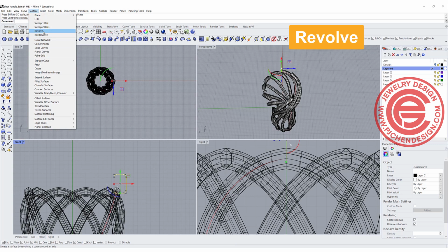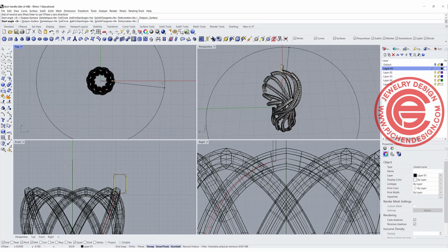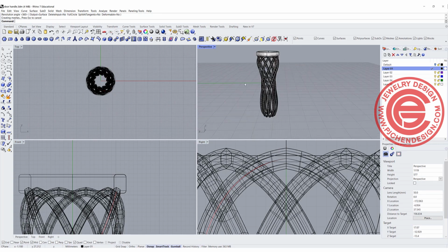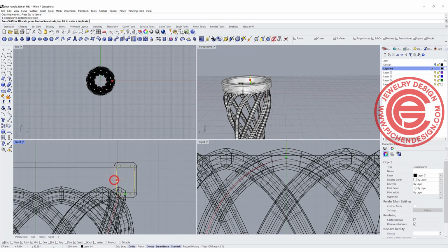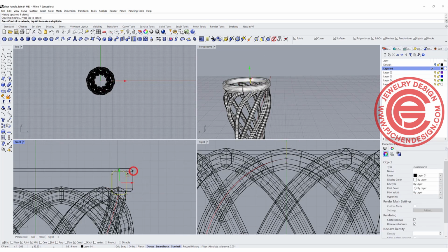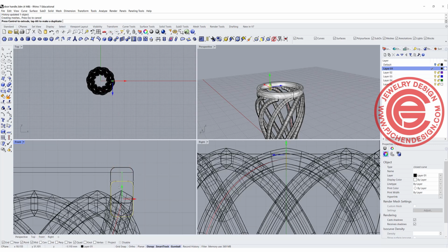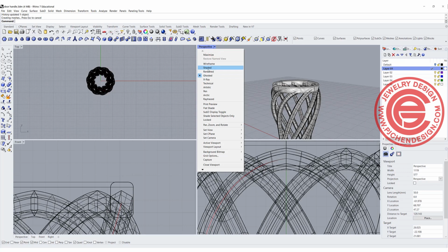That's using the revolve command again, and we want to snap into the 0. So type 0, move your mouse to the front view, click on it, and back in the top view we want 360 degrees. Before you press enter, go to the bottom where you have record history and record it, and then we'll get something like this. If you feel this is way too heavy for all this wire, because we recorded history, we can scale it down and it will change the shape at once. I just want to cover all of them without a big opening there.